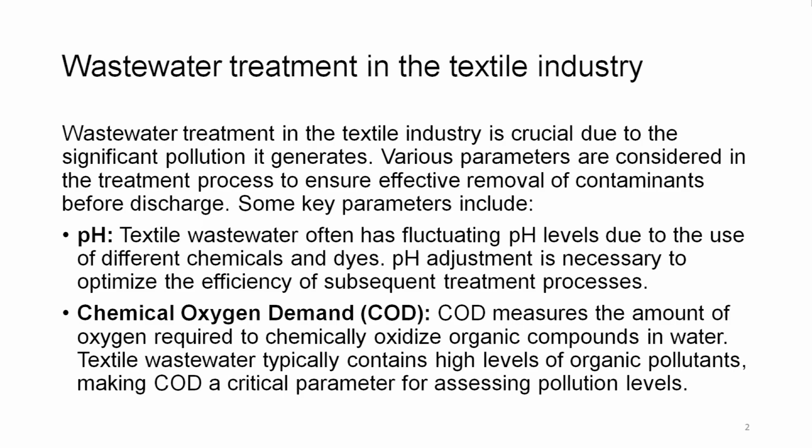Chemical oxygen demand, COD. COD measures the amount of oxygen required to chemically oxidize organic compounds in water. Textile wastewater typically contains high levels of organic pollutants, making COD a critical parameter for assessing pollution level. Now, if the dissolved oxygen is not enough and the organic pollutants are more in quantity, the degradation will not take place very easily.